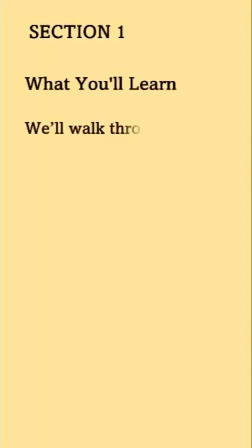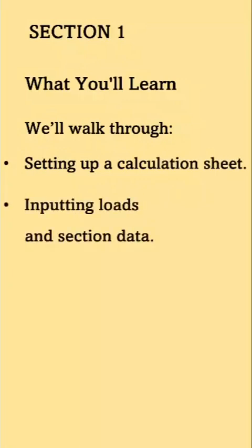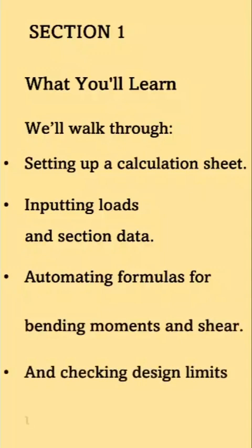Section 1. What you will learn. We will walk you through setting up a calculation sheet, inputting loads and section data, automating formulas for bending moment and shear force, and checking design limits using Eurocode formulas.